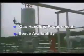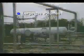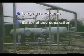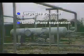Selection of a separator type is based primarily on gas handling requirements and space availability. A horizontal separator is normally more efficient at handling large volumes of gas, and because of its large interfacial areas, it has better phase separation capability. It does not handle solids as well as a vertical separator, and it requires more space.